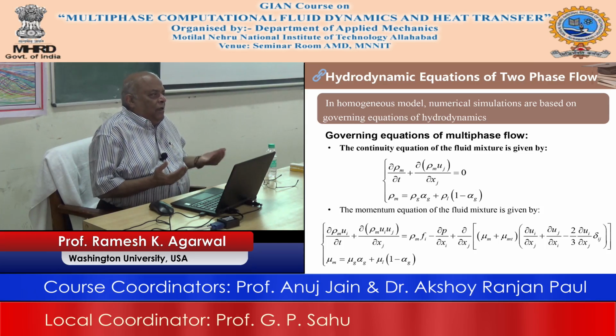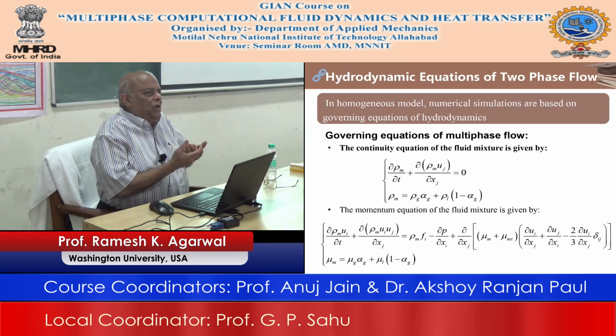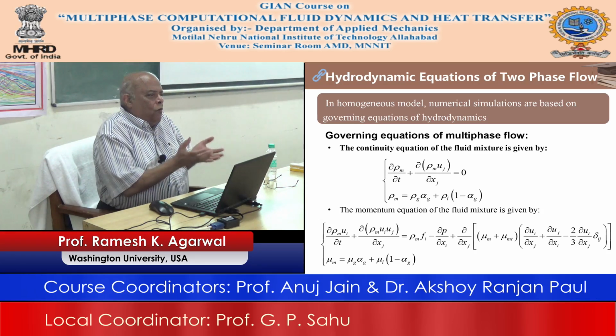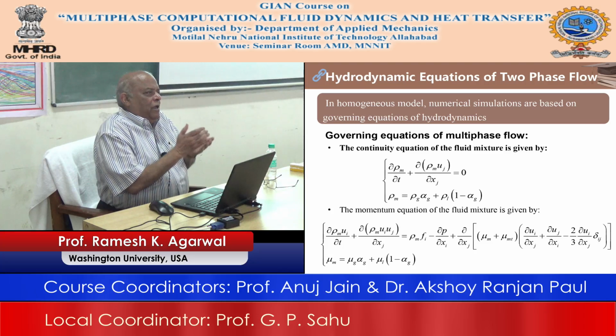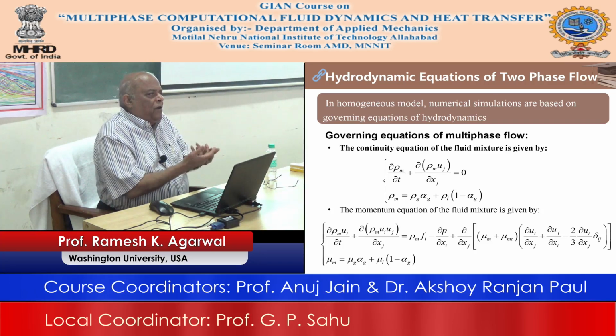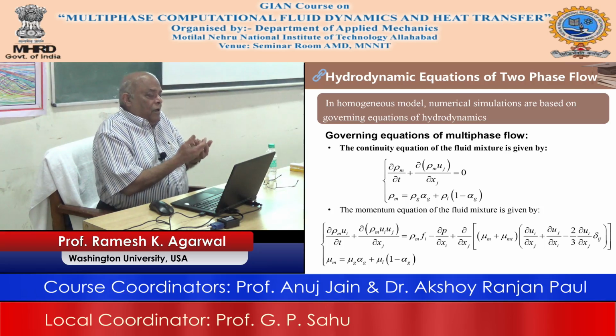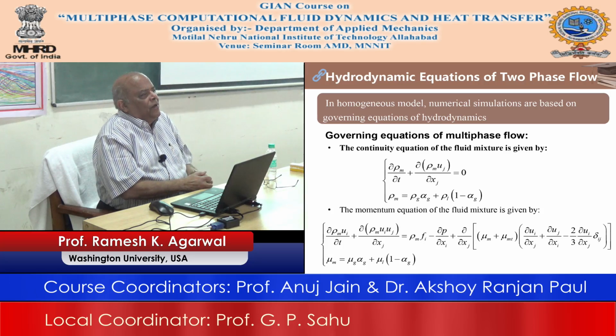Because the problem is very different, the only thing the same is the continuity equation and momentum equation, and the method is the same, that the whole cluster of these bubbles is being treated as one mass of air. Okay, so you have a certain fraction of air and a certain fraction of liquid, or water, but that keeps on changing in the iterative process. It's not fixed.